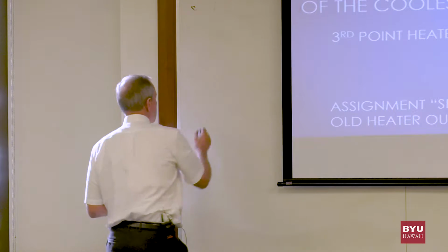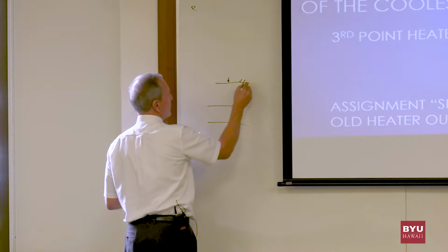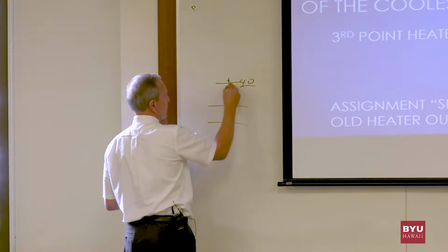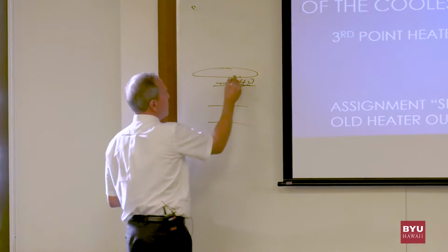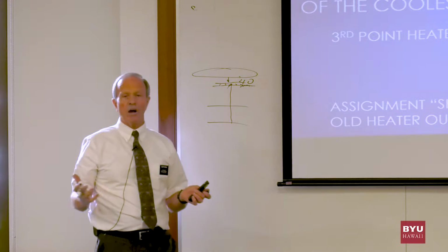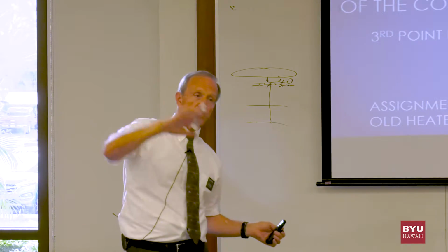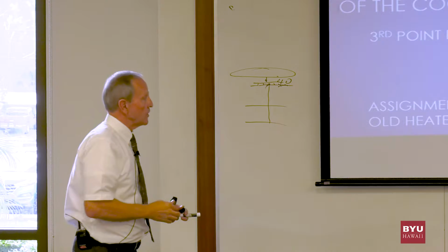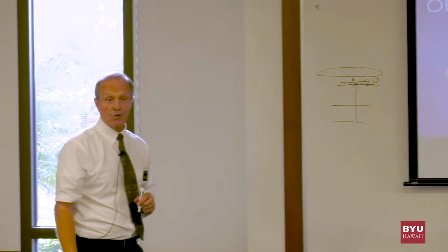So what these guys did is this is your ground level. This is sitting up here 40 feet in the air. It's not really in the air, but it's 40 feet from the ground on this grading. And here's this vessel. Well, they put it so far back in there that they thought, how are you going to get these out? We had to cut out huge steam headers. We had to cut out this. We had to do that to even start to get this thing. So they said, get rid of that and put a brand new one in. And so that was the challenge.